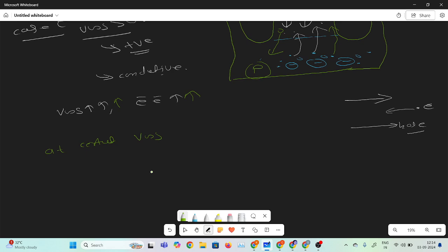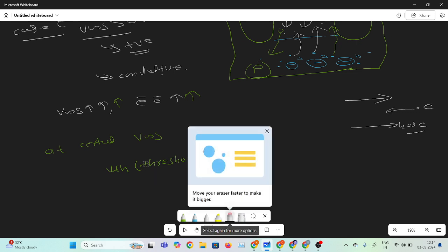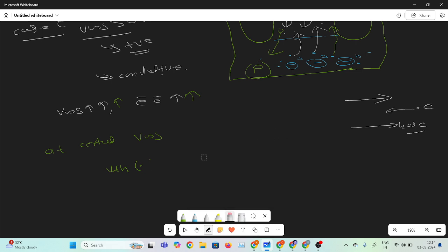What I am telling, understand? Here I am talking about VTH, the threshold voltage. If we are increasing the positive voltage on the gate terminal, at a certain value of the gate voltage, a sufficient number of charge carriers will come to the channel, and the channel starts to invert. So this is the threshold voltage.